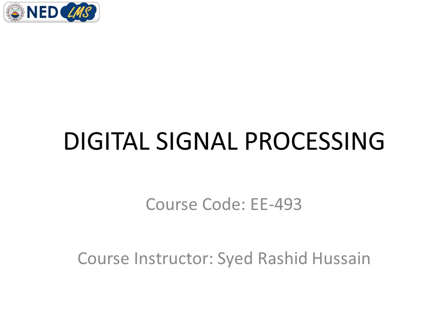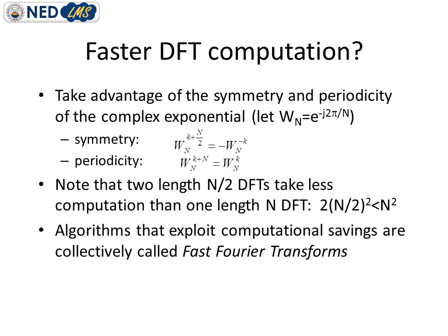So in this lecture, we will discuss FFT in detail, what this technique is about and how we can compute the frequency spectrum of any signal with the help of fast Fourier transform. Basically, FFT is based on the DFT analysis and synthesis equation. As we know, the basis function, e raised to power minus j 2 pi over n, is a rotating vector.